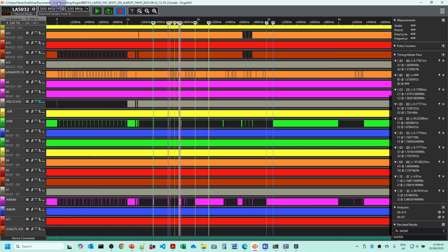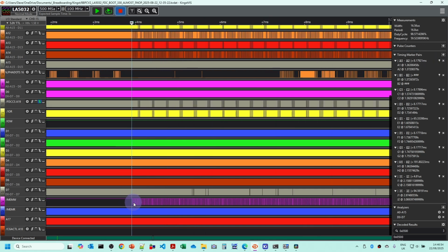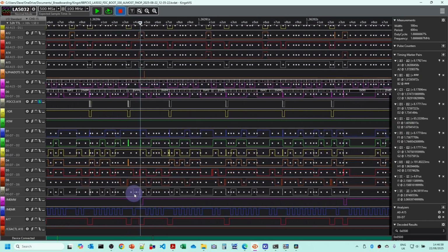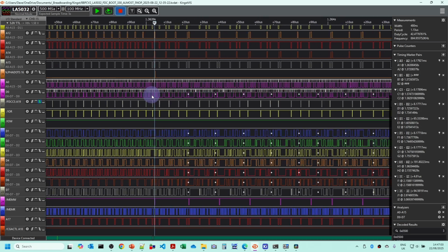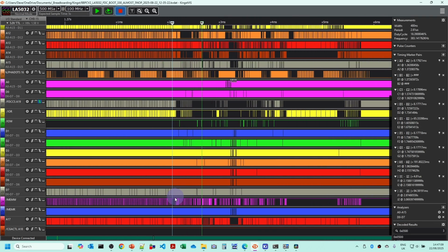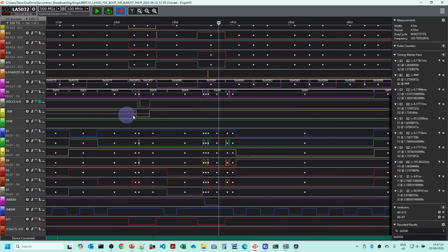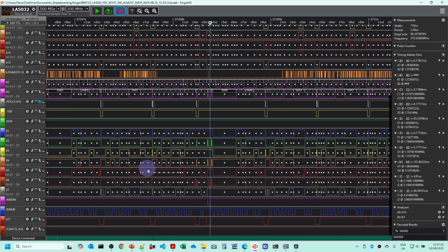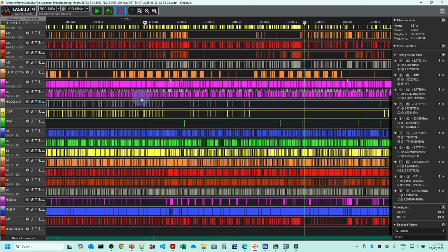So this is the logic analyzer for the address bus and data bus and the various I/O signals. If we have a quick look at the timing markers here, the first one indicates where we're actually loading the boot sector. This is 7C00 and the E8 is the first byte we expect. And then at the end we expect the 55AA magic bytes that we have for the boot sector. We've got AA, and the previous one is 55. So the boot sector is loaded correctly.